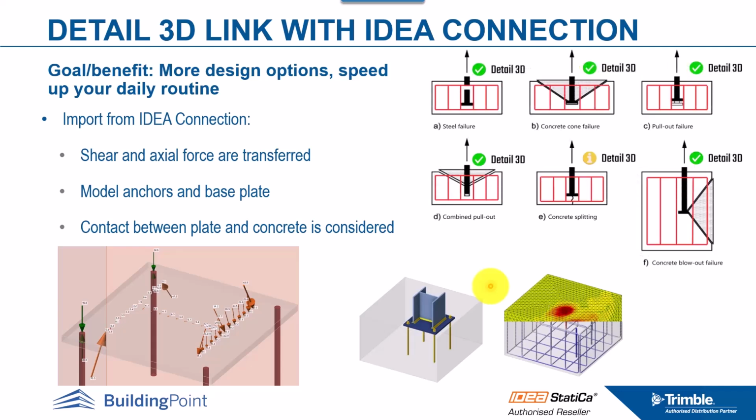So here, as you can see, by using the Detail 3D application, you can simply check the anchors, and it doesn't matter what geometry of the base plate or the concrete you have, the number of anchors, or the length of the anchor. You can just send the information from IDEA StatiCa Connection to IDEA StatiCa Detail, and simply design them.